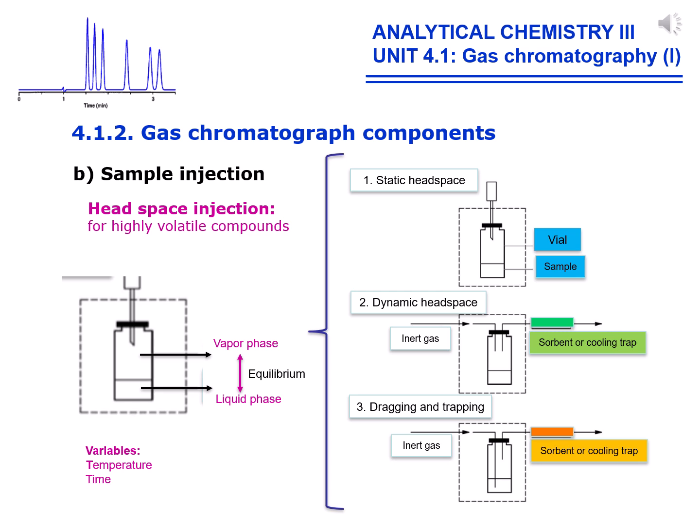The static headspace: a fixed time of equilibration is applied and the estimated amount is sampled with the syringe and injected into the gas chromatograph. The main problem of this modality is the lack of reproducibility, as it's sometimes difficult to know when equilibration is fully established. The dynamic headspace: there is no equilibration time.